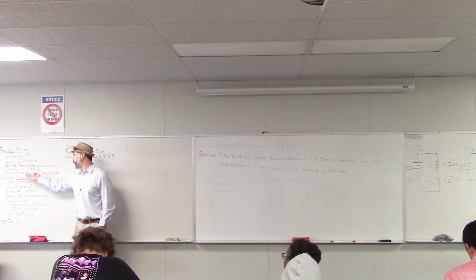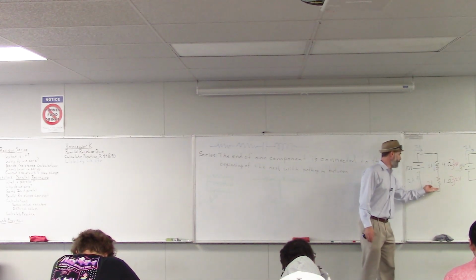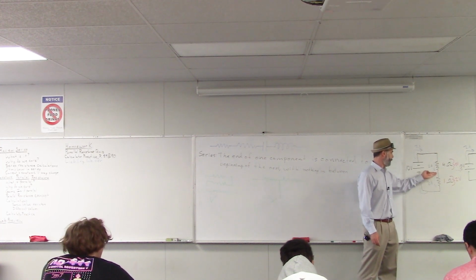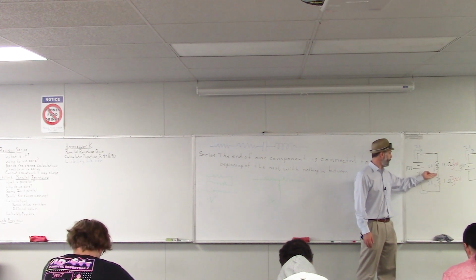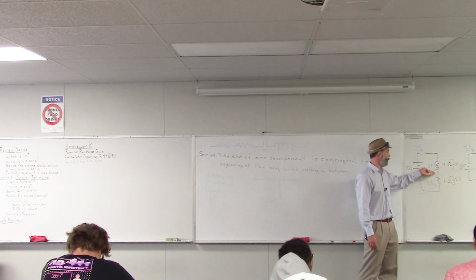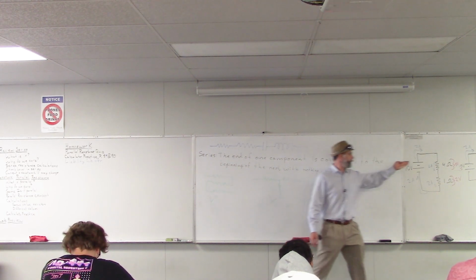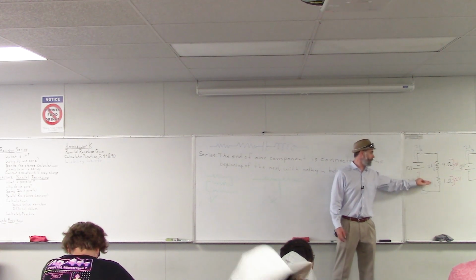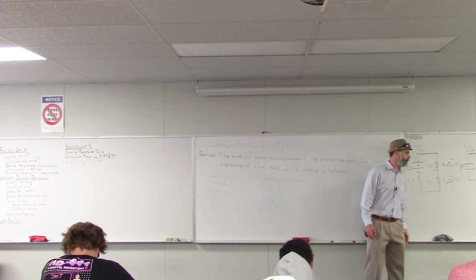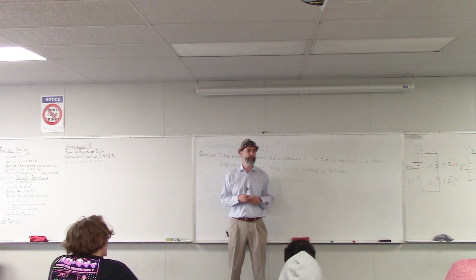And we can see that when we have a series circuit like this, the current is going to be the same for all of the components in that series because that's basically the definition of series. The end of one component is connected to the beginning of the next. So all the current that flows out of one has to flow into the next one. It has nowhere else to go. So for a series circuit, the current will be the same for all of the components, but the voltage may be different. Could you have a series circuit where the voltage is the same for each component?